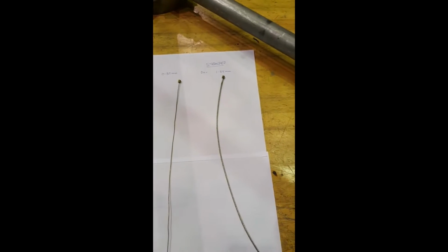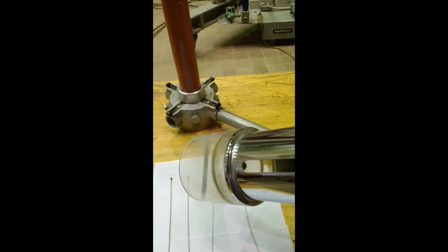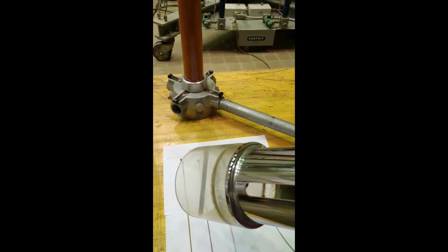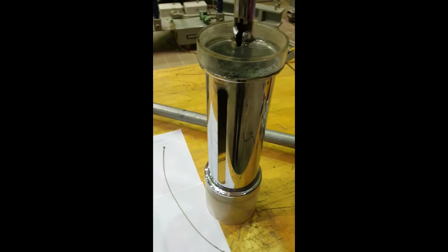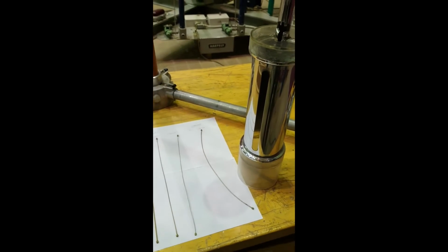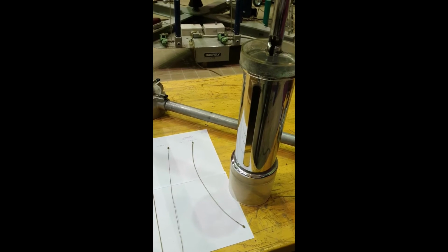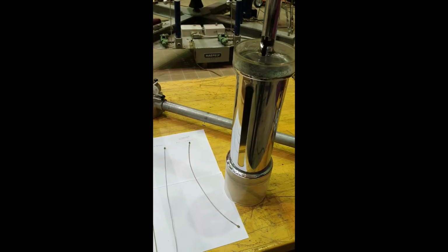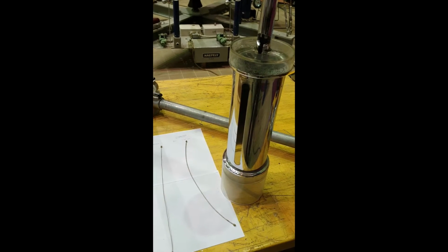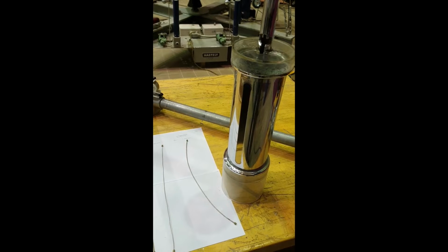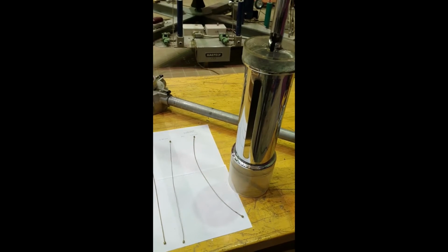These will all be individually put inside this coaxial geometry, and then the onset voltage will be found for them under DC voltages, both positive polarity as well as negative polarity. We may not be getting positive polarity, as the doctor explained in the theoretical class. Positive has few pulses at the peak and a lower frequency, whereas negative has a frequency in the kilohertz range.